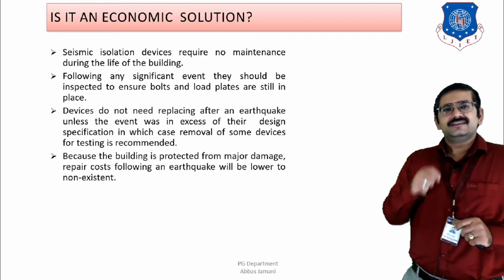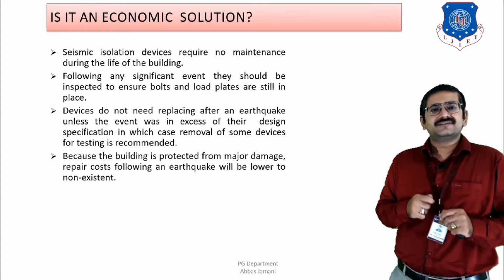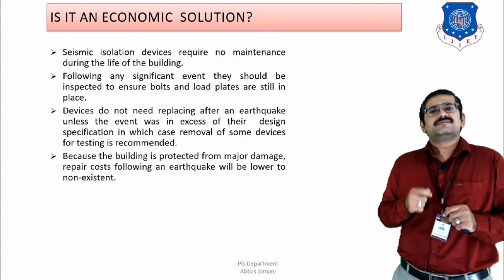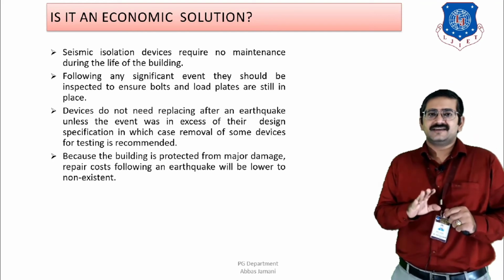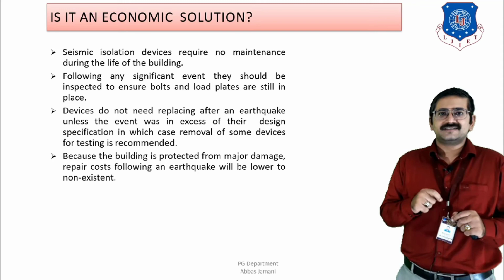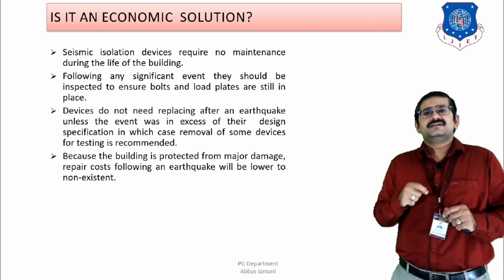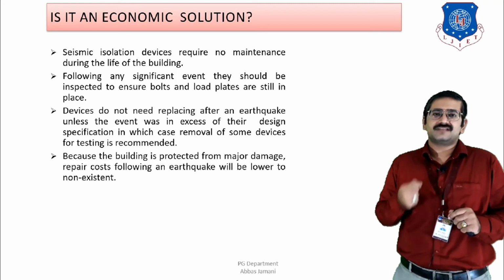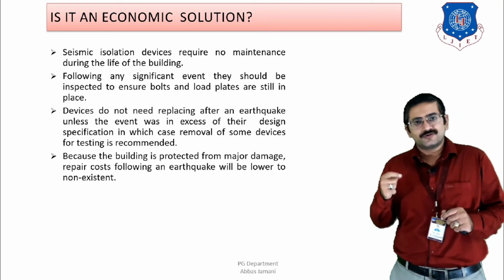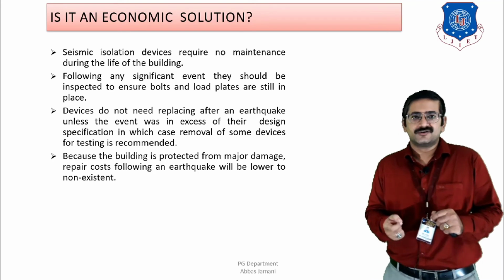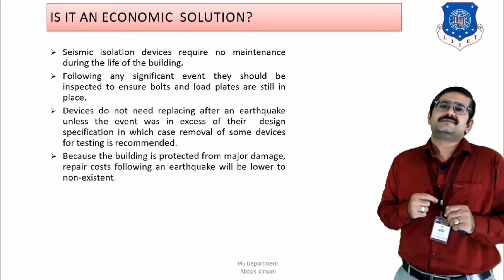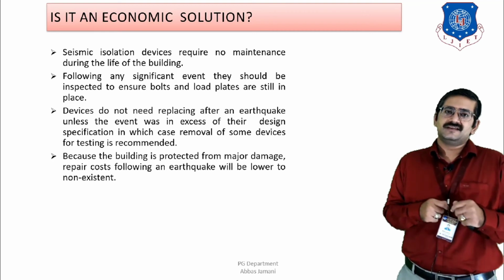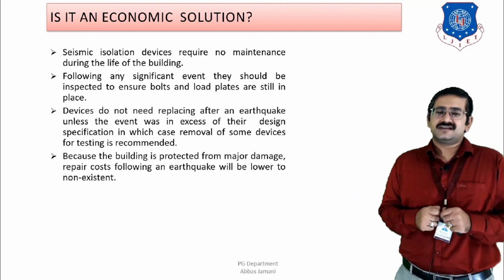right? Then the other advantage is that following any significant event, immediate inspection of bolts and plates can be done to make sure they are in place. If there is any damage, because the event has introduced a large amount of lateral forces higher than the ones that were calculated, then local repair of this base isolation system can be done, and retrofitting is going to be a very easy process, and no other retrofitting schemes are likely to be adopted in